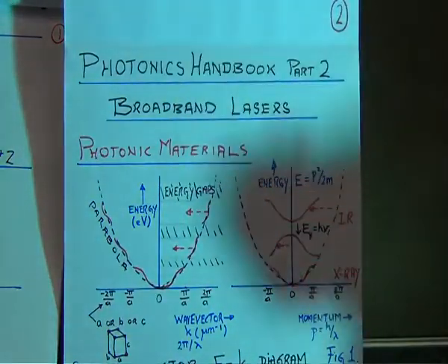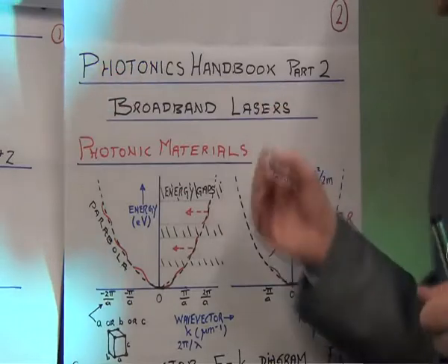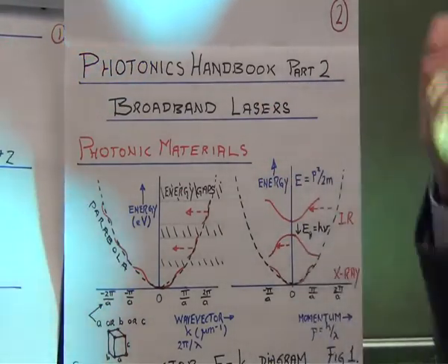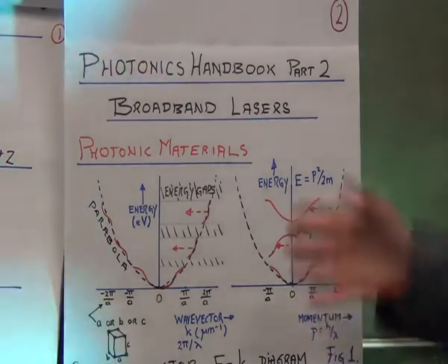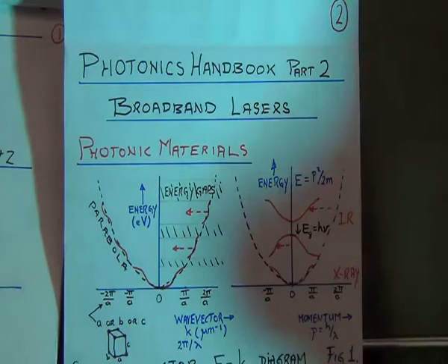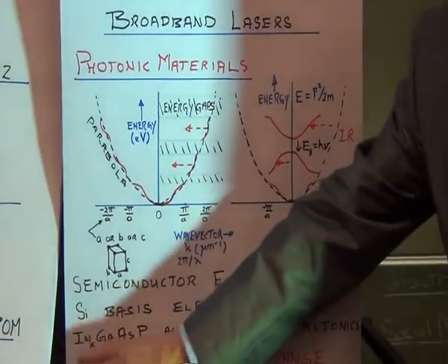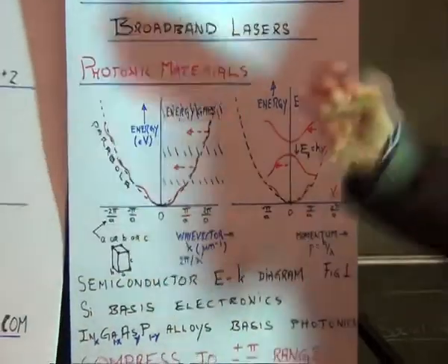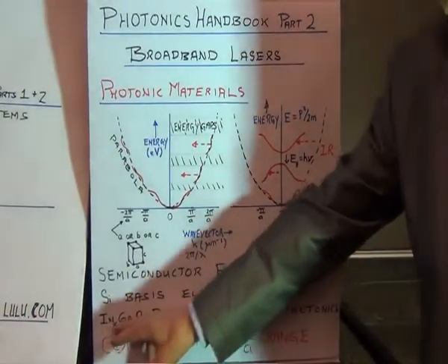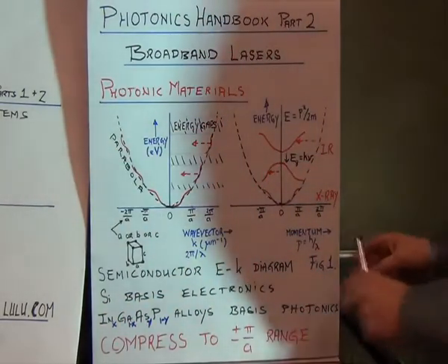If you add up them all, you might find it's less than picowatts, maybe femtowatts. For communications, we need milliwatts. That's 1 billion times higher. Therefore, the candidates we have to settle on are these alloys, like gallium arsenide, indium phosphide, mixes of 3 of these, which are called ternary alloys, ternary 3-5s, and a mix of all 4 of them is called a quaternary 3-5 alloy.